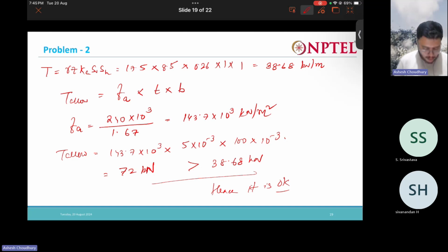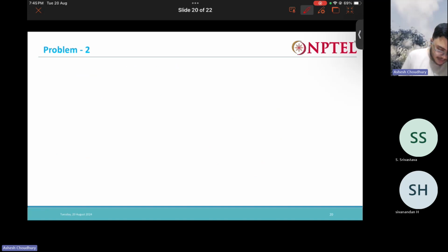Now next we have to check our length. You have to calculate the length. How to calculate the length of the reinforcement? It is nothing but LR plus LE. LR is from the geometry. And what is the embedment length? This we already calculated, it is a fixed value, 4.14.